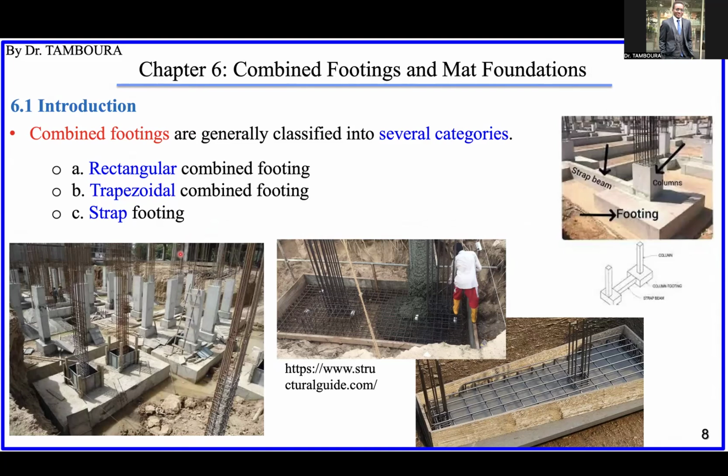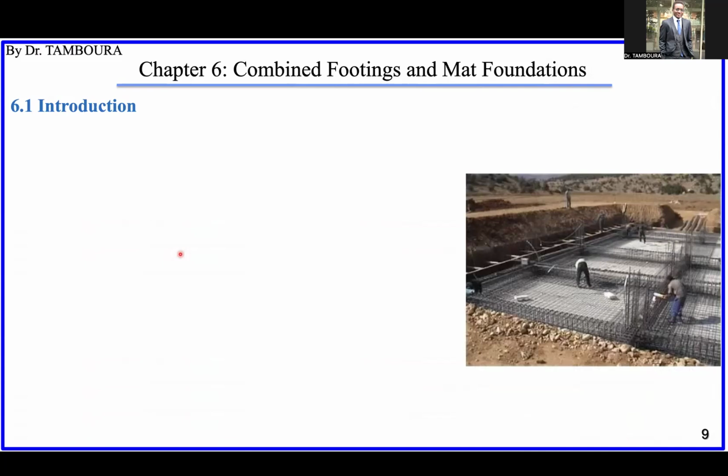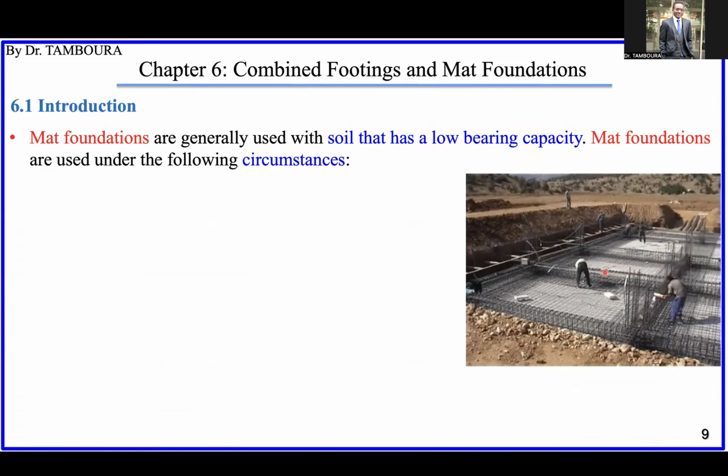Yeah. Next, let's see what we can say about the mat foundation. Okay, so this mat foundation, we generally use them where the soil has low bearing capacity. So we have some very special circumstances where we choose to go for the mat foundation.